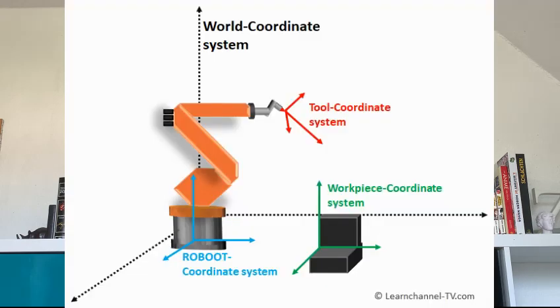So here you can see that x is in a 90-degree angle in the current frame, but let's say you have a motor here and a motor here, also spinning in the same direction, means that this x, which I'll just say is red, has to be in a 90-degree angle to this z and to this z, because this is the previous one and this is the current one. A frame is basically just a coordinate system you put on every joint.